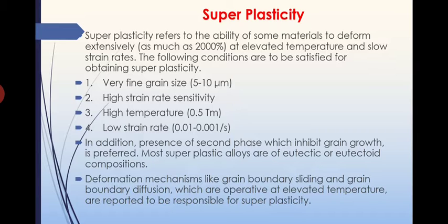See, even though they are metal, they will behave something like liquid. They will show liquid like properties. That is what is known as superplasticity. So the advantage of having superplasticity is we can mold that metal into any required shape, of course, by applying high temperature. These properties are usually exhibited at high temperatures.